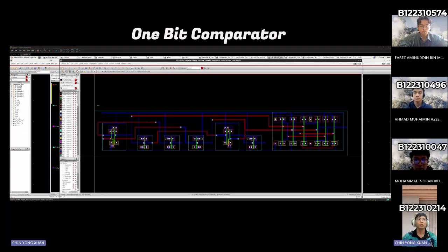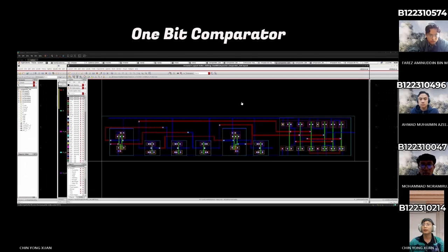So this is the final top level comparator layout. We then used layout XL to generate this top level comparator. We also used the abutment technique to seamlessly share the VDD and GND rails across all cells to save silicon area. For routing, we established a strict layer direction using metal 1 for short vertical connections inside the cells, and metal 2 for horizontal signal highways like our A and B input tracks. We prevent short circuits. Thank you, Tim.